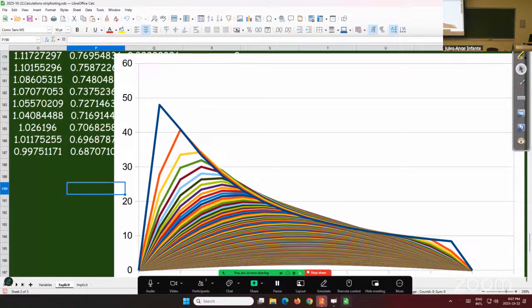Right, basically what you're saying is with the depth, right? At time zero, near the middle of that clay layer, time zero is not the worst pore pressure you're gonna get. So if you were doing this as a design and you just took your pore pressure right at time zero, yes, you're not being conservative by using the pore pressure in the middle of the clay layer at time zero. Okay?